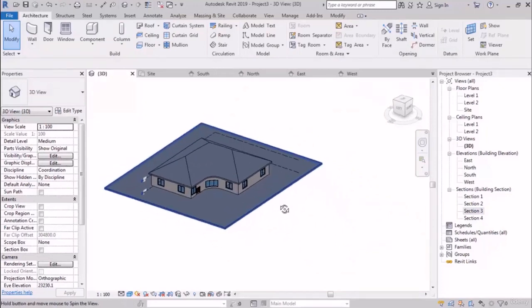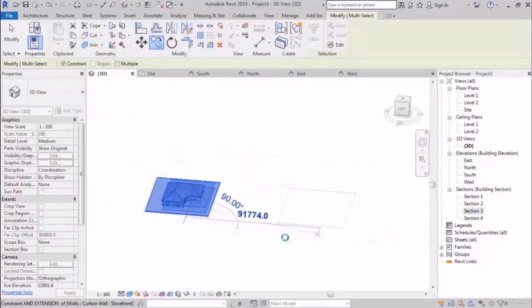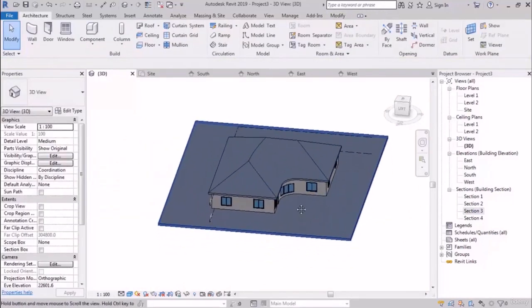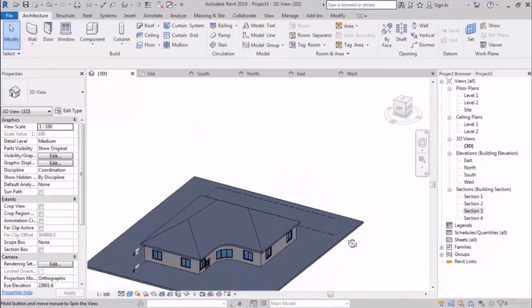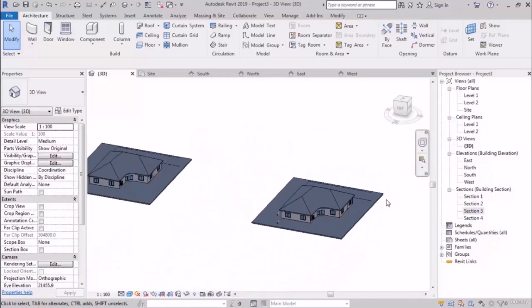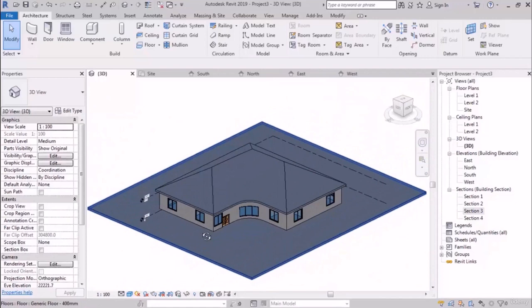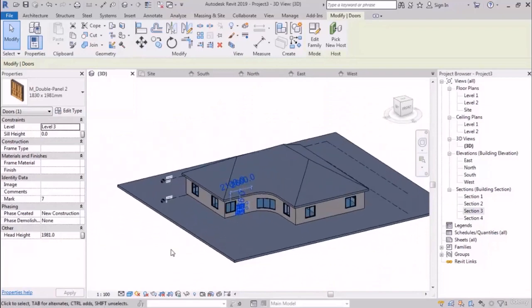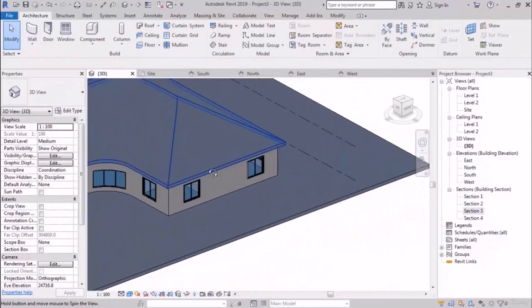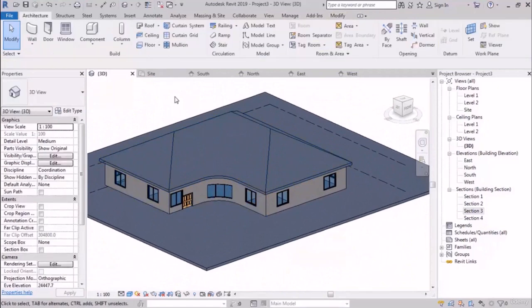What does it mean? Imagine we have two blocks in our project. We have a house here, and let me get a copy of it. Another house here. Now we want to work on this one. While we are working on this, when we turn our view, it will disappear. You might have faced it in other software too. But why does that happen? It's because now the center of your turning is the other house. So what do we do? We choose another object from the next house as the center of turning, for example, a door. Now the center of the turning will be here. And if you want to work on the previous house, again click on another object to be your center.